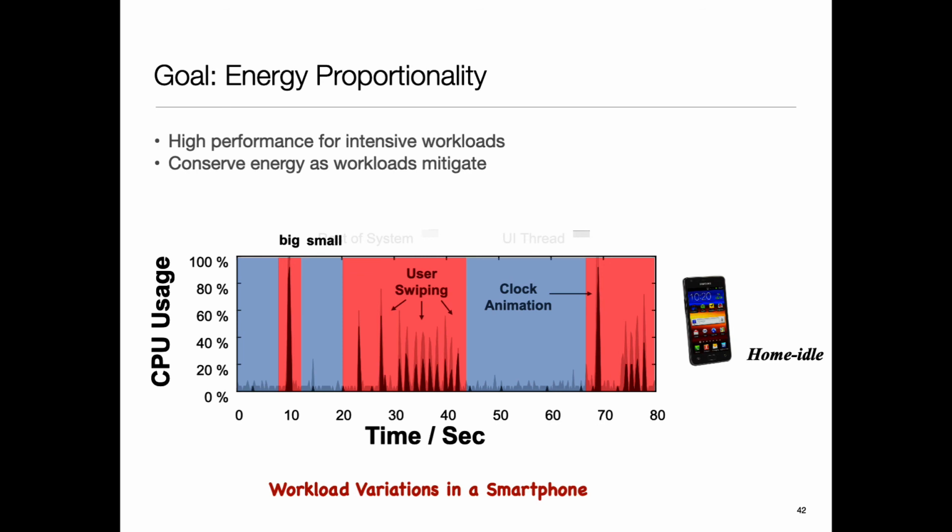Other smart stuff: as the user is bringing the finger closer, these are capacitive screens, maybe I can detect that the finger is coming closer and switch the processor to a high performance mode, ready before the finger touches the screen. So there are all sorts of clever things you can imagine doing, but the basic idea is that I dial down the resources according to the activity that is happening and try to hide the effect of latency. Okay? So that's the idea.